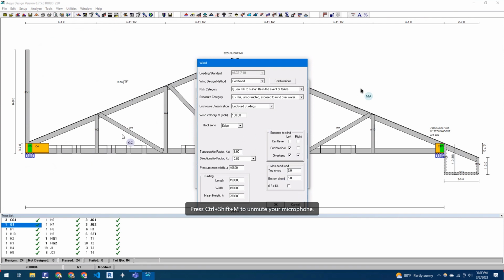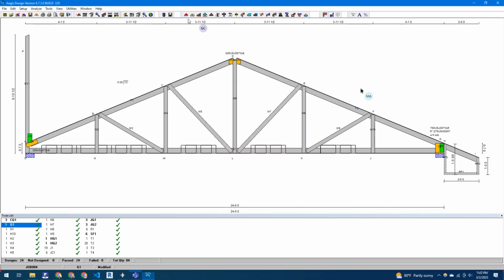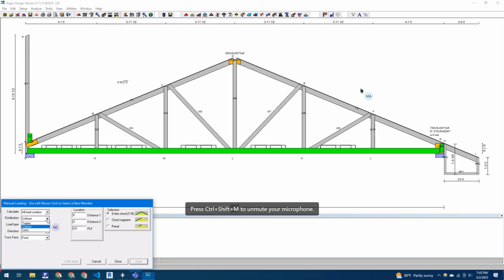But in order to get the full load on the parapet, you have to add a point load up here, which depends on what the EOR is telling you to do. So it would put a load blowing at it, but you still have to put some kind of load up here, but you have to do it in the, let's see, concentrated.